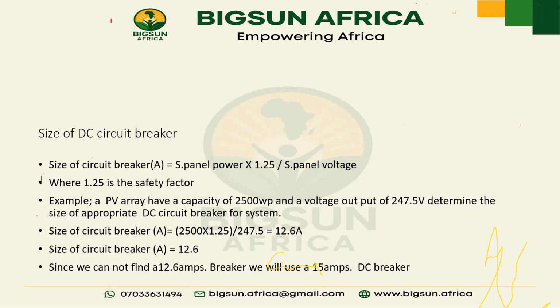So let's look at the size of the circuit breaker, which is equal to what? Solar panel power times the safety factor, all over the solar panel voltage. The solar panel voltage is the overall connection voltage. You understand? Are we ready to proceed?